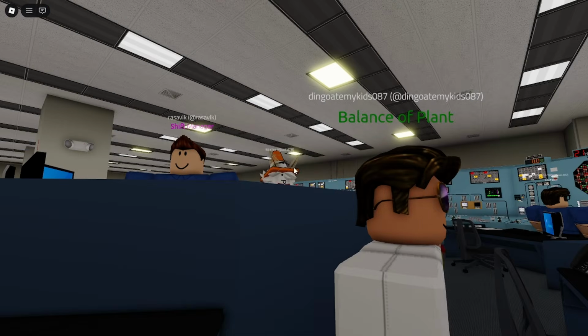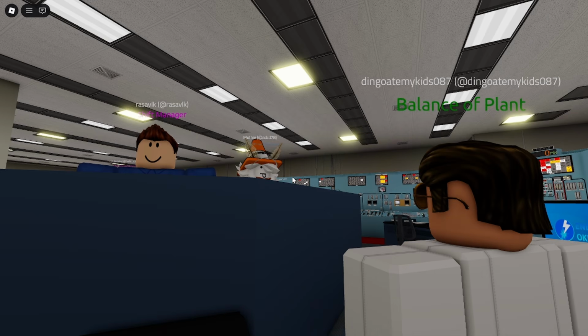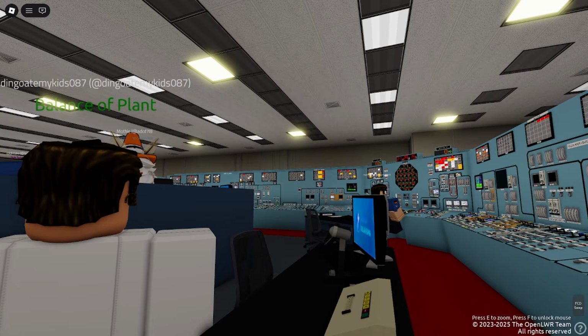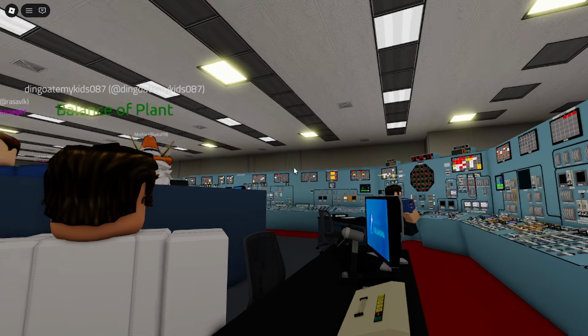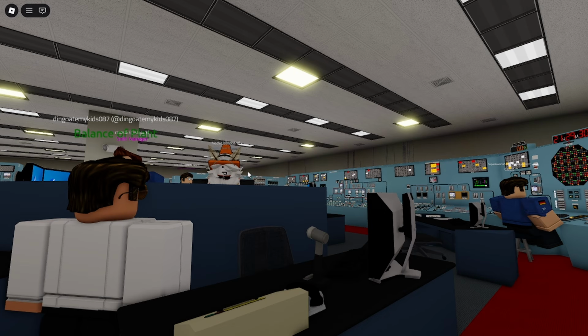CRS? Yep. Equipment operators have restored service water pump B. I understand Field Ops has restored SWB pump. That is correct. Alright, BOP? Yes. I would like you to start SWB, and then I would like you to call Field Ops and have them reset the lockout for DG2 and run it up. Understand, do you want me to start service water pump B and instruct Field Ops to reset DG2 lockout and start DG2? That's correct.